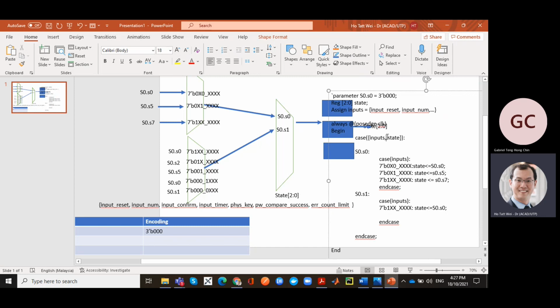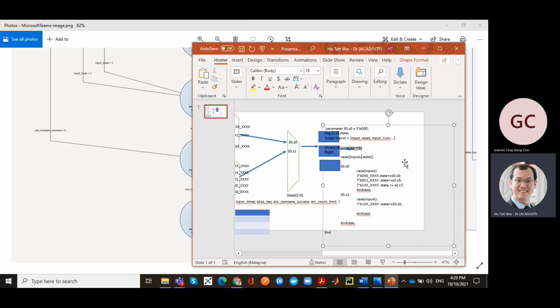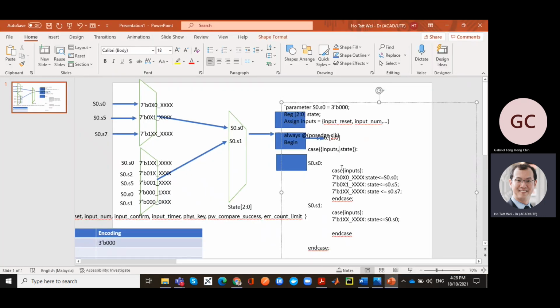So if you want to have it simpler, of course you can concatenate. You can concatenate two states so you don't have the nested state. But in this implementation I don't concatenate, so that you can actually see it. But if I were to write it, I would concatenate, because actually it's just a single 10-bit mask also can already, right? It's just you're setting the bits. You can condition only on the 10 bits, which is the state on the first 3 bits followed by the rest.